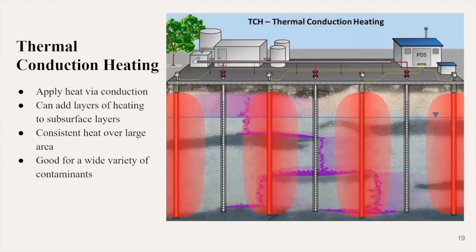Because one of the advantages of this treatment is it's very consistent over the area. It can be a large area or a small area. So that temperature control is very important. It's also good for a wide variety of soil types, including gravel, clay, sand, and tight soil layers. So as we discussed earlier, that permeability and porosity doesn't have to be very open for this to work because it heats everything and then sucks it out. And this also doesn't have to be saturated. You can do above or below the water table.